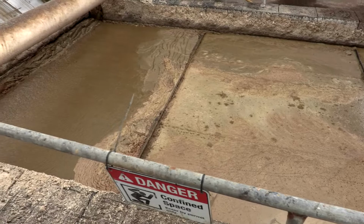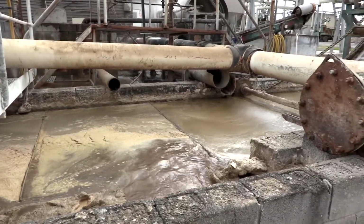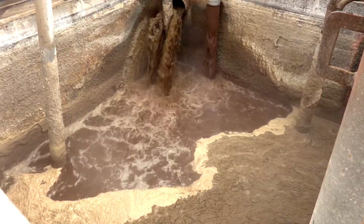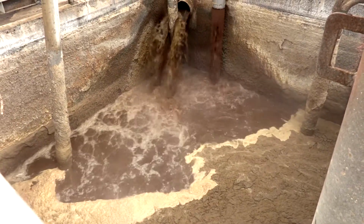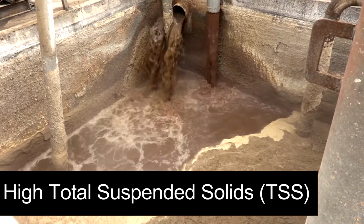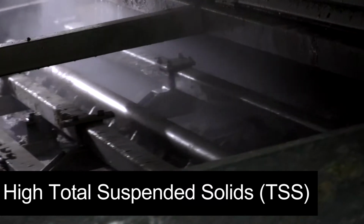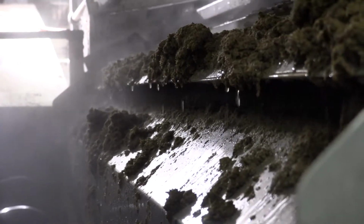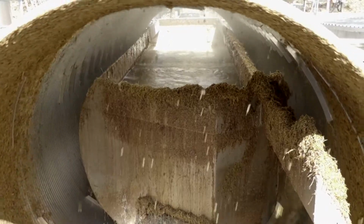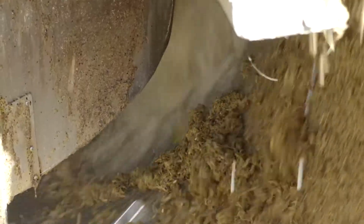Meat processing wastewater can be difficult to treat properly compared to other industrial wastewaters due to its high concentration of contaminants such as suspended solids, oils and grease. Typically, the raw wastewater has high concentrations of suspended solids, particularly in green streams. These suspended solids arise from operations such as emptying of paunch and manure or grit from stockyards. If not removed during upstream treatment, these solids settle out in downstream ponds and fill them rapidly.